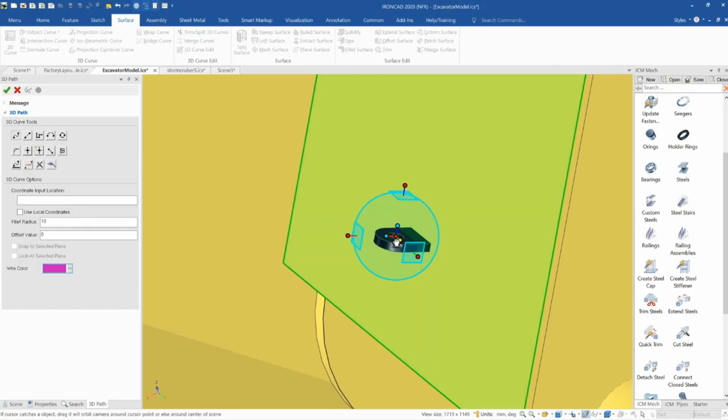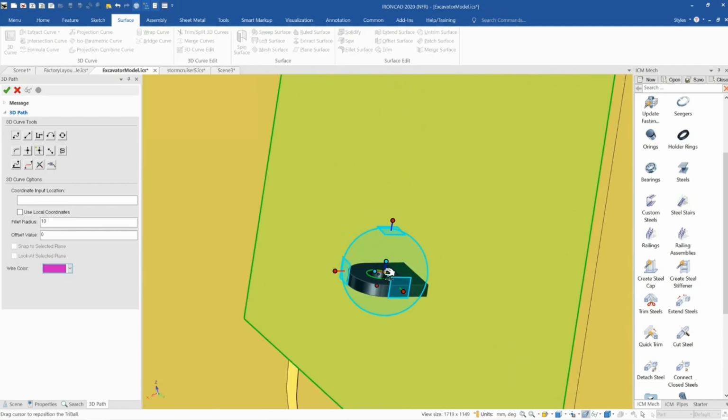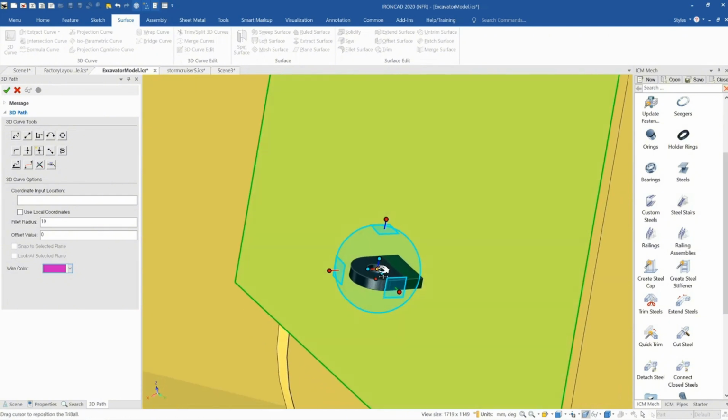So I'm going to hold down the Shift key and snap into position there. So if you hold down the Shift key whilst hovering over circumference, it'll snap to the center. You can also right click and just select a center point and then click the circumference as well. Now we can actually move that precisely. So we can type in precise dimensions here. For example, I could type in 50 millimeters and hit enter.